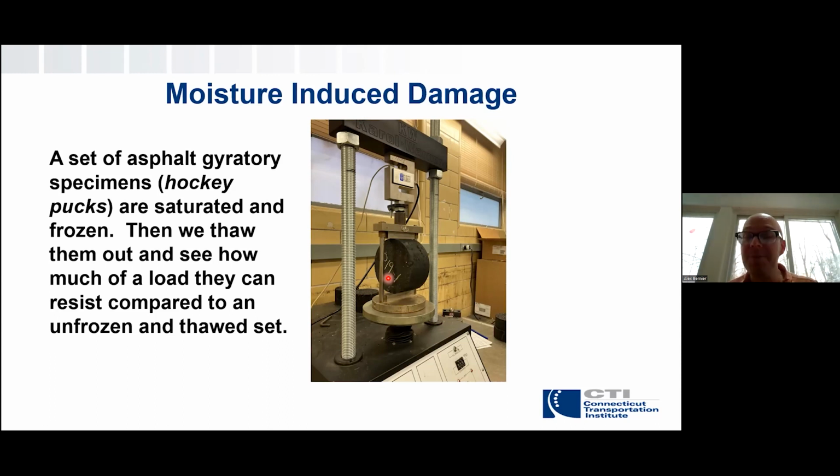Now, asphalt experiences a lot of tension, tensile forces, and actually those are what's more likely to cause its failure compared to compression. However, in this configuration where you stand it on its side, we're actually testing both failure criteria at once inside the specimen.